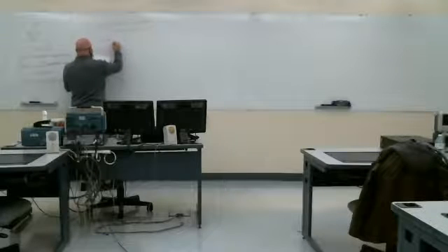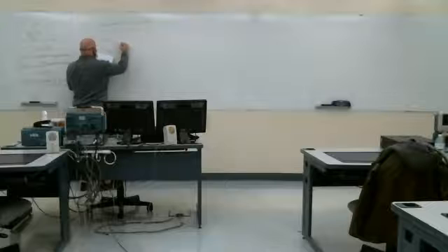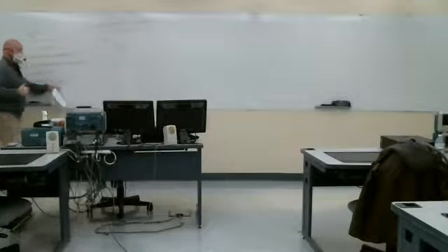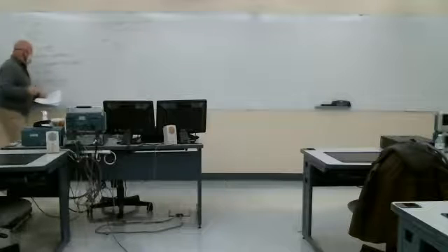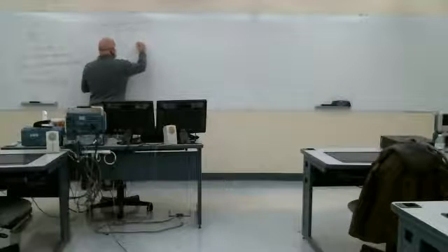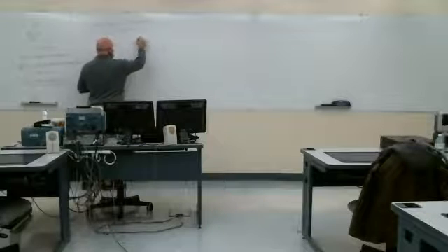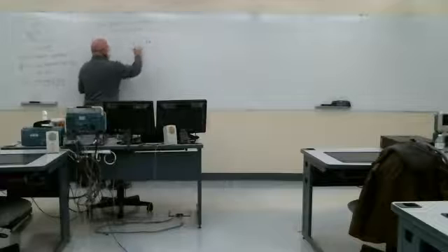And then our maximum voltage would be when this dot product is equal to 1. And that is equal to 2 pi F0 A times B0. Okay. And there's some useful information there. Some of it you might be able to guess at, based on what we know about Faraday's law, that the larger the loop area, the greater the maximum voltage.